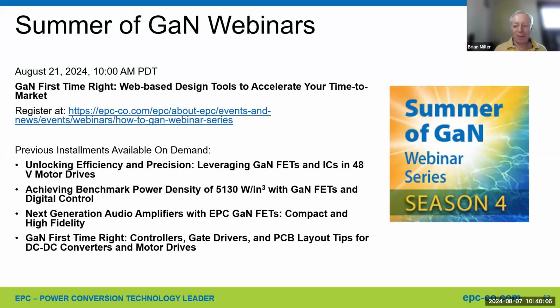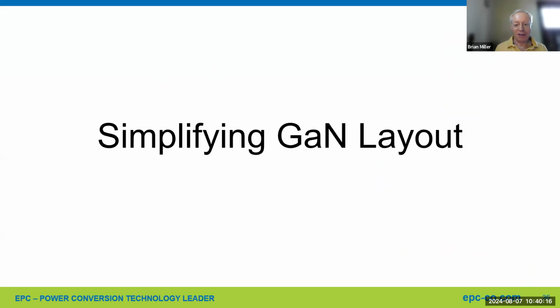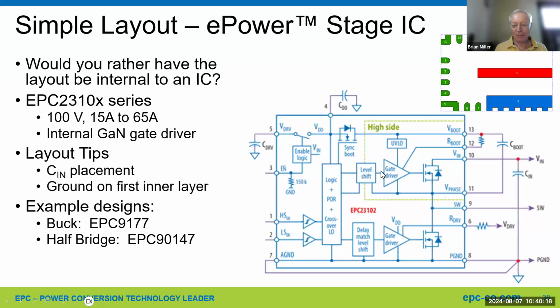Yes, it works very well, with the caveat that it's good to regulate the voltage on the high side. That's actually a very good question. I could use this example here. Inside the typical driver, whether it's an IC or, for example, even the TI driver, they regulate the top. So you might think, well, bootstrapping, is that a good idea? Yes, it is, because there's a limit in most of these, an LDO or some kind of limit that has an ideal output for the top FET.